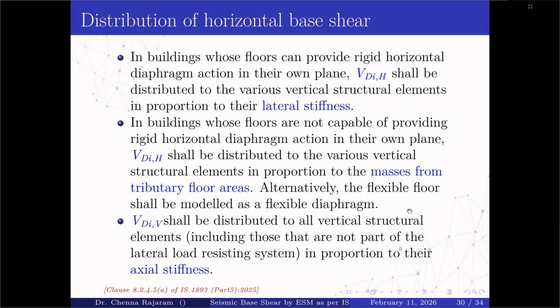In buildings whose floors are not capable of providing rigid horizontal diaphragm action in their own plane, V_i^DH shall be distributed to the various vertical structural elements in proportion to the mass from tributary floor areas. Alternatively, the flexible floor shall be modeled as a flexible diaphragm.